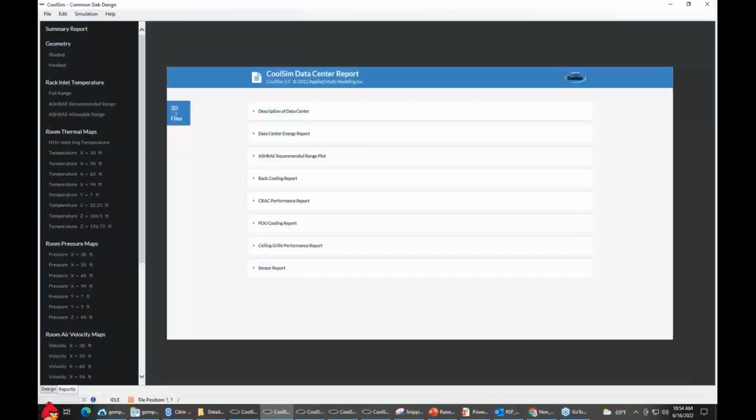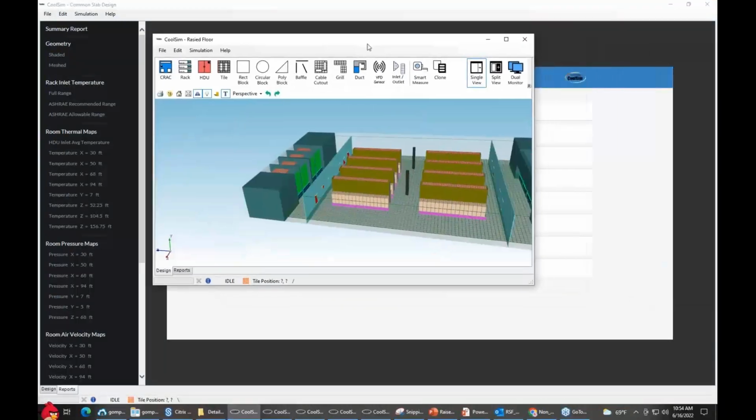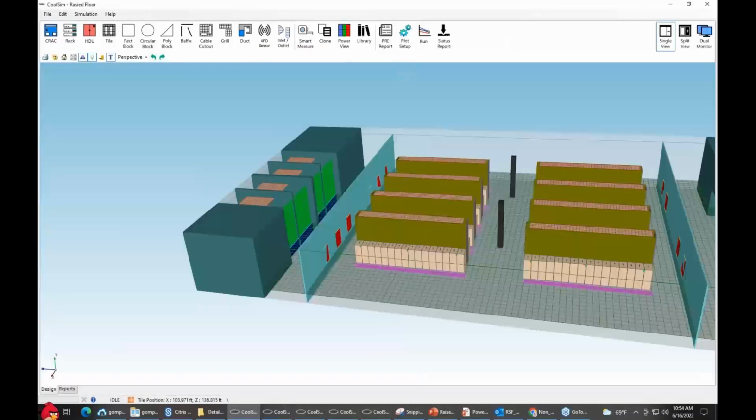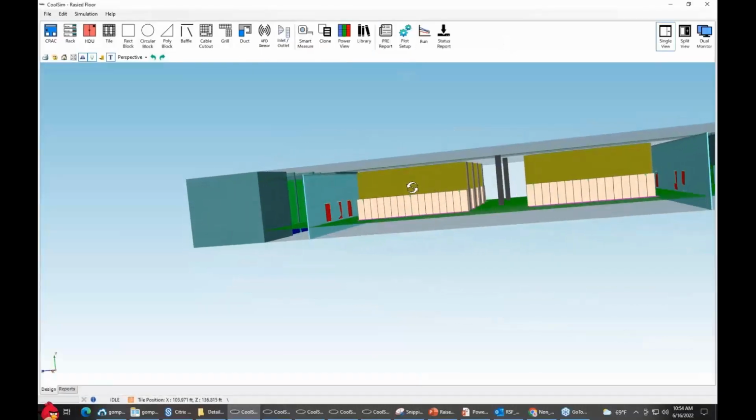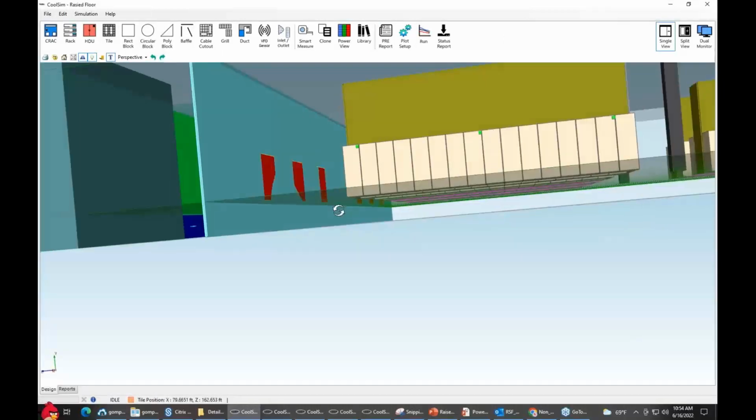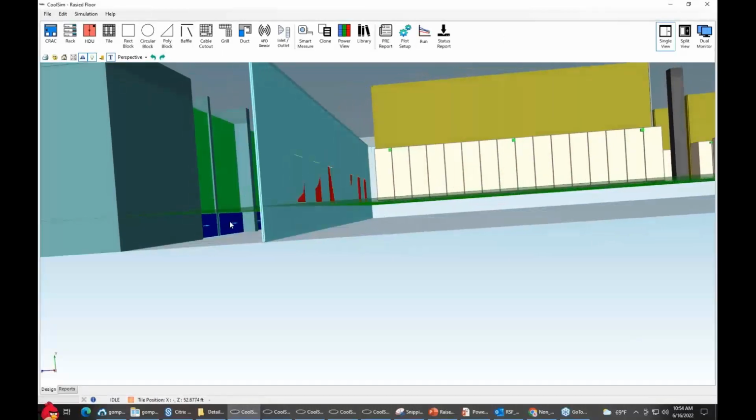Now, in contrast, I have this one, which is the same exact design. Let me drag it over. But I put a floor plenum underneath it. And in this case, my floor plenum's not that deep. And the other thing I did here, which I simply took those air handlers and stuck them under the floor, which is not quite right because the cross-sectional area here is fairly small, which means the velocities are going to be high. If you were to do this design, it would be best to flip these 90 degrees and drive the air straight down, let it bounce off the floor, let some of that momentum decline, so that you have higher static pressure.